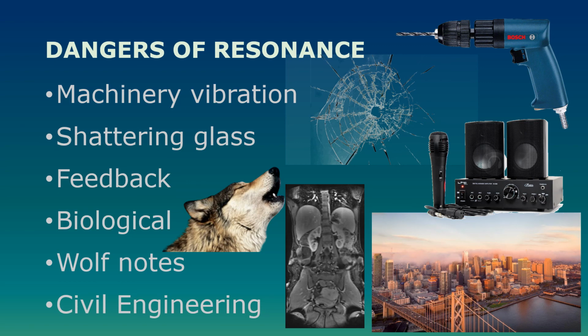And then probably the most famous is concepts with civil engineering. There are examples throughout history of large buildings falling foul of resonance issues. Essentially, the most obvious one to consider would be any city that is built near an earthquake, and if an earthquake occurs at a certain frequency and a skyscraper or a bridge has the same natural frequency, then the amplitude of vibration will be much higher and can cause a great deal more damage. So buildings, suspension bridges and things need to be damped so that those situations don't occur.